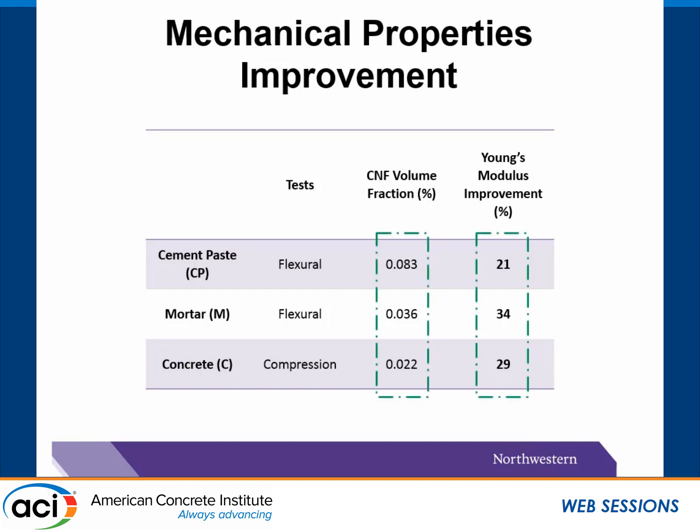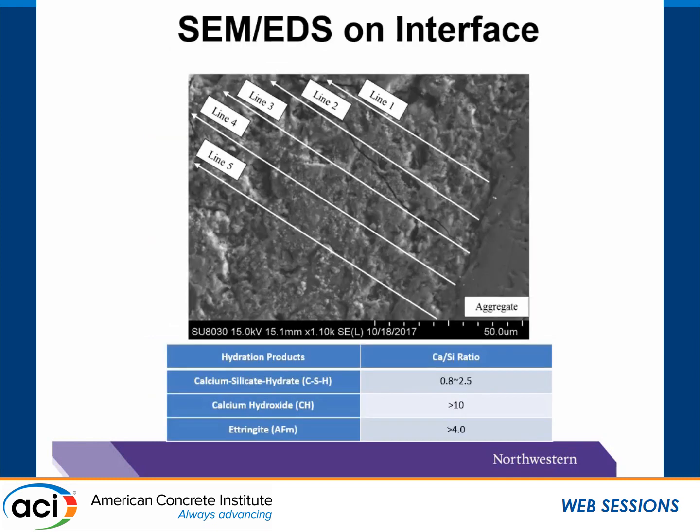Also, the significant improvement on the Young's modulus is particularly interesting for us, especially when there is not much improvement on the compressive strength. To investigate the interface between the bulk paste and the aggregate, we performed a SEM EDS test with concrete samples with or without the addition of CNF.